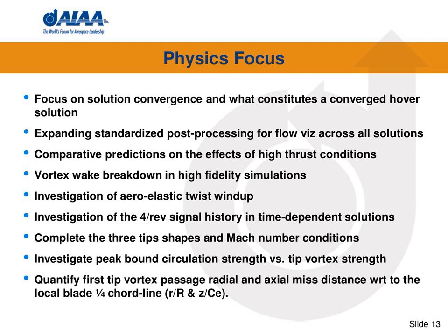The key issue here is the focus on the physics, because often what ends up happening is you can get good results without getting the physics right. So the focus was to dig into the 3D data and try to get all the physics, like what happens to the wake under high stress conditions, or, if you have an elastic twist, what does that do to your wake? There are so many things you can look into, but not all of them have the same degree of effect on the ultimate loads. But the ability to predict a new rotor blade often hinges upon whether you get this right.